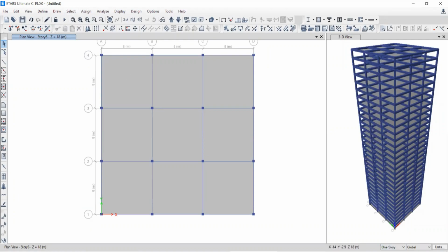See, I'm going to click here. How many selections are there? One shell, 4 edges. One shell is in selection. Now I'm going to change it to all story. Now I click over this again. Then see how many selections are there? 31 shells. Now from base to top, all the selection has been made for this particular position. All the slabs are now in selection.